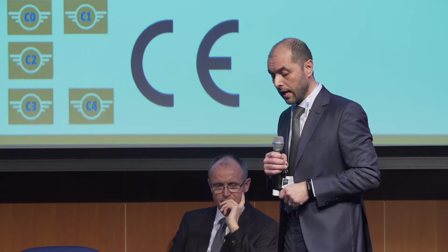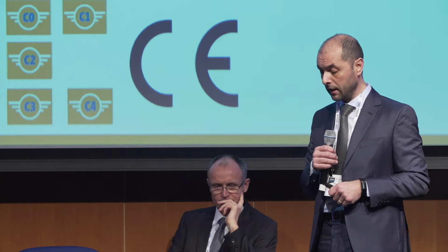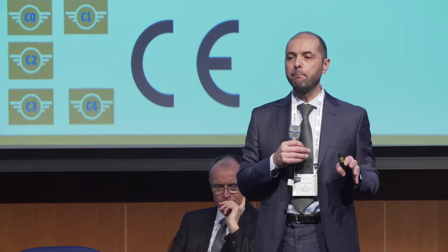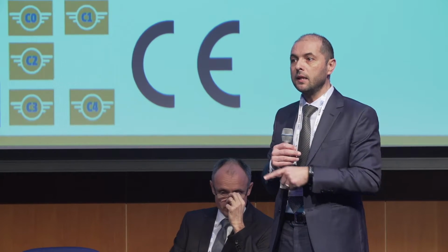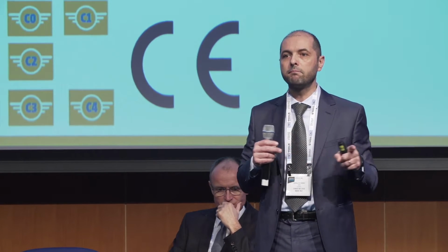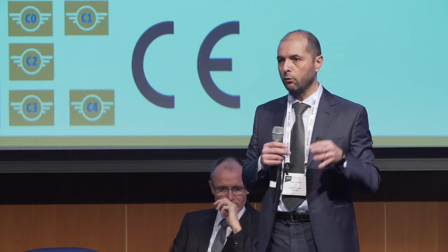Never carry dangerous goods or never drop material. And important, no autonomous operation in the open category. When I say autonomous operation, I mean operation where the aircraft is capable to fly without the intervention of the pilot. I'm not talking about automatic operation. So this means that I can still upload some flight plan, and the aircraft is flying by itself, but I need always to keep the aircraft in sight. If there is any problem, all the time I need to be able to take control and maybe land or do something different that was not planned.